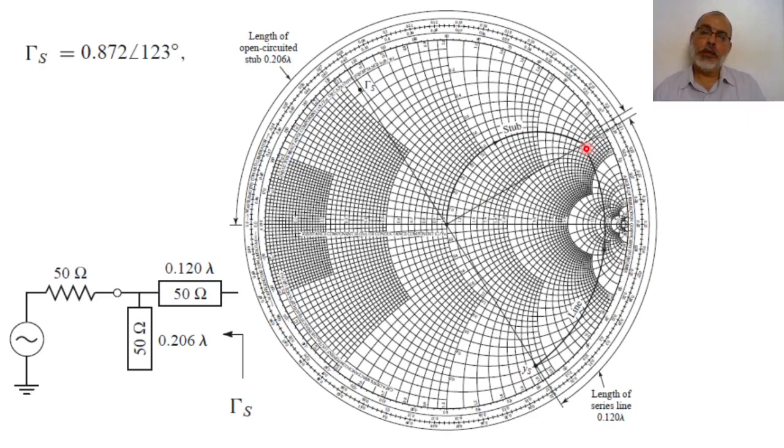Right? So this is the distance required such that the input admittance goes from the required admittance YS to be 1 plus jB. This distance is calculated here, the distance towards the load. So I'm going through the dimensions here on the axis, moving towards the load, not towards the source, in this direction.